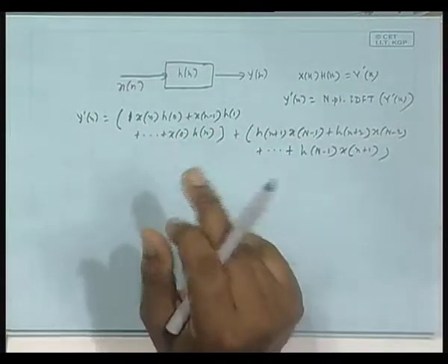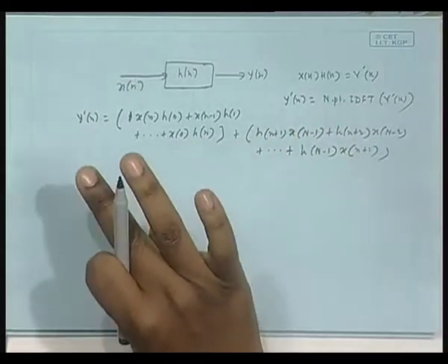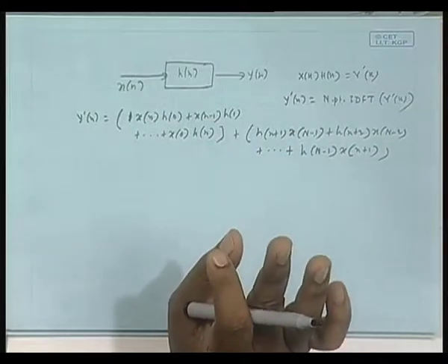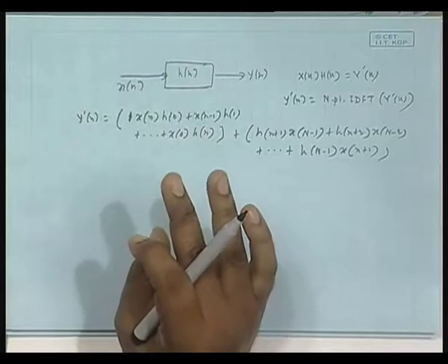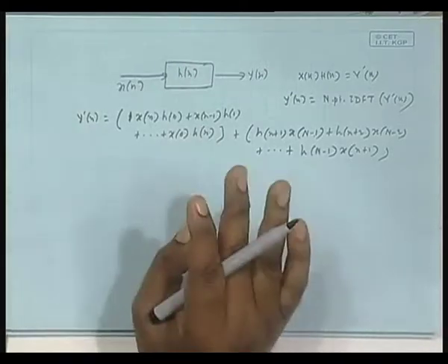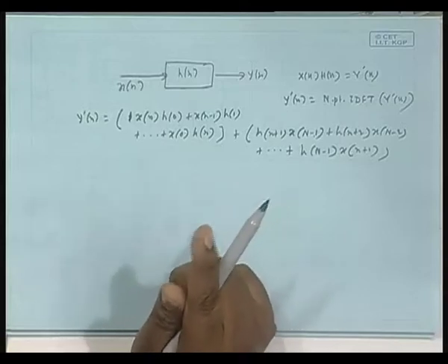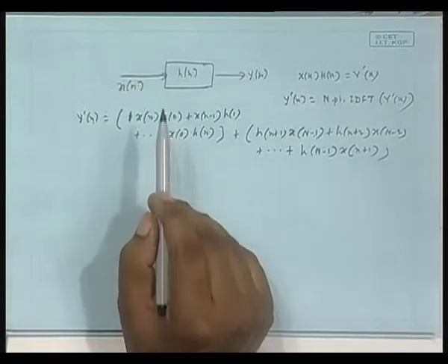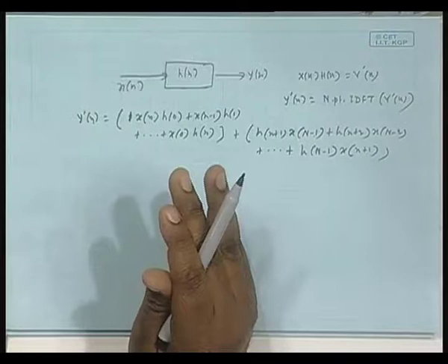After that, the next two steps are common with linear convolution. You reverse the entire infinite sequence. Mind you, after reversal it also remains periodic. A periodic sequence, when you time reverse it, still remains periodic, and then you shift it by the amount at which you want to carry out the convolution. Like here you are finding the convolution at n, where n can be 0, 1 up to capital N minus 1, that is our range. So, shift it to the right by small n.